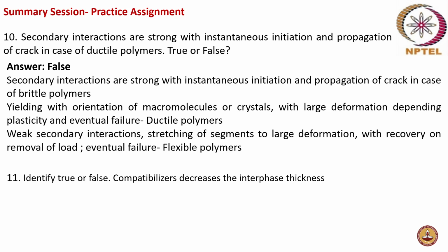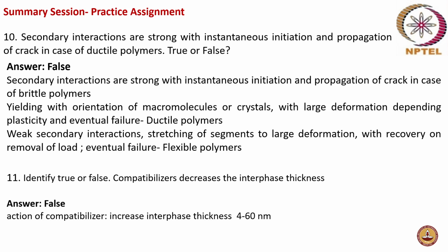Yes, you are right. It's false. It actually increases. The action of compatibilizers is that they increase the interface thickness, for example, 4 to 60 nm. So there are many more interactions and a better interface, and the two polymers are compatibilized in that way by increasing the interface thickness.